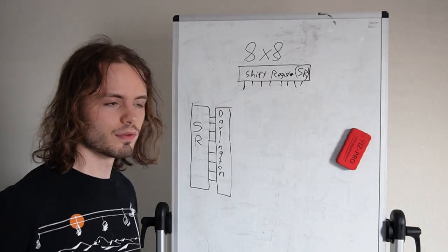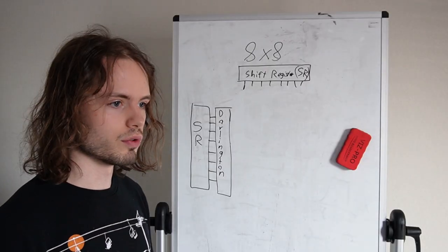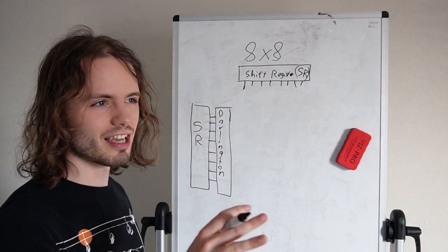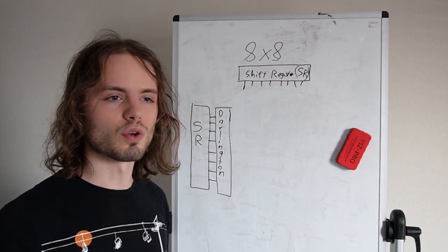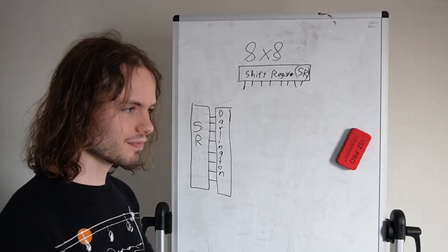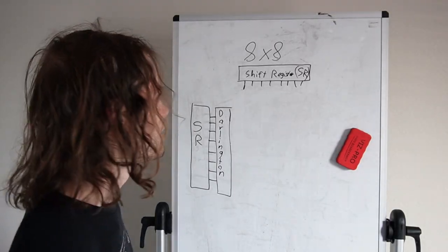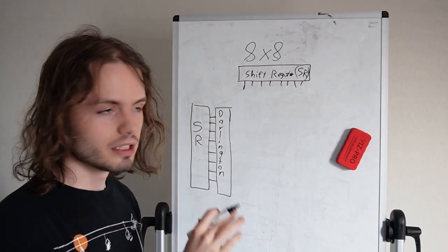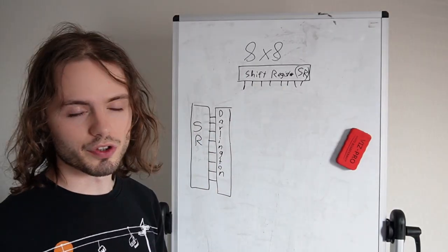And if I want to go past 8x8, if I want to do 16x16 or 32x32, I think the calculation for 32x32 is over 1,000 LEDs. So it becomes unreasonable to try to directly drive every one. So that's why I'm using these registers to handle that, to reduce the pressure on the GPIOs.